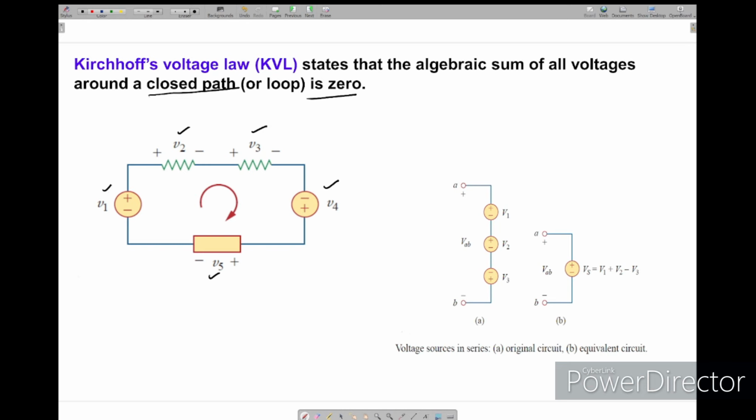So how can we write the KVL in any closed loop? First we'll see, this is a voltage source which is having terminal negative here, and direction of the current we take like this. So current is like this. Already I mentioned this is the resistor, passive element. Wherever the current is entering, first we'll take positive, and again current is coming like this, entering at this terminal, so we have taken positive, and same current is continuing. This is also one element, you can take a resistor, entering at this terminal, so we are taking positive and negative. So one loop we formed.